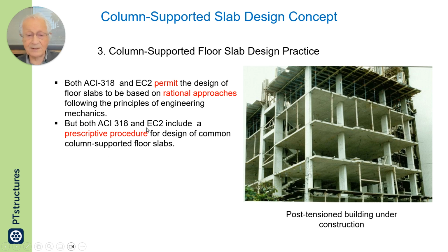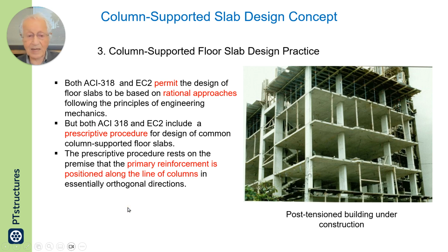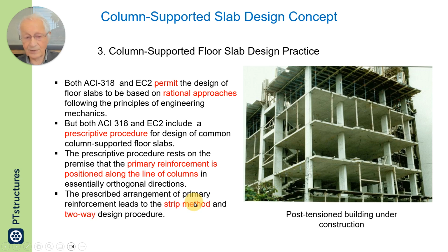Both 318 and EC2 include a prescriptive procedure, although both of them clearly permit using any other rational approach. The prescriptive procedure rests on the premise that the primary reinforcement is positioned along the line of columns. The prescribed arrangement of primary reinforcement leads to the strip method and two-way system.